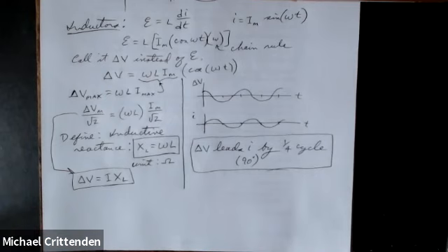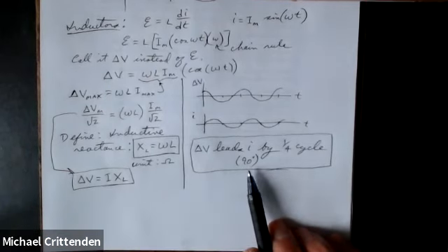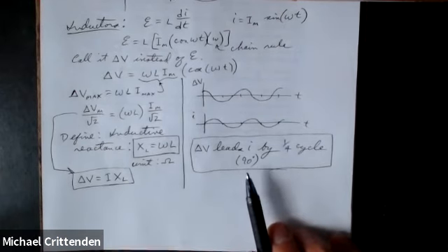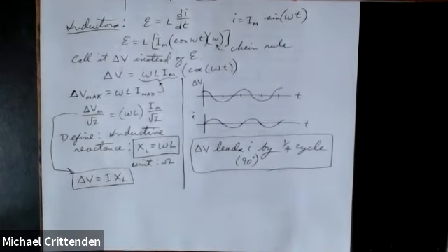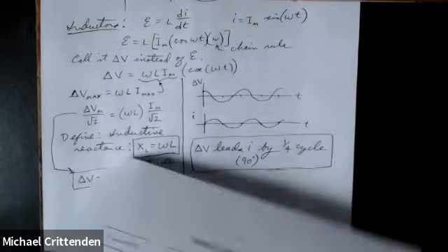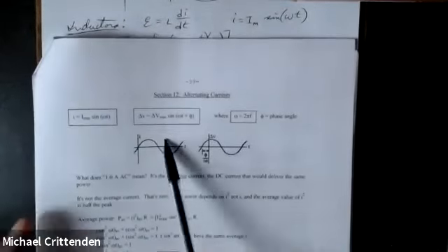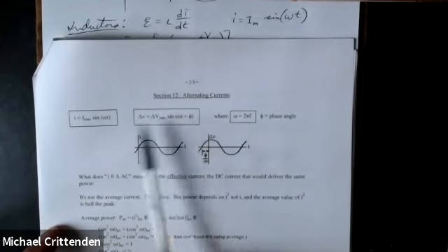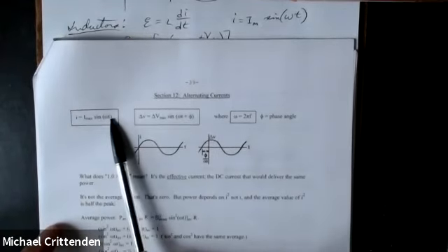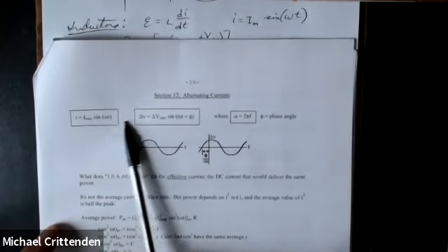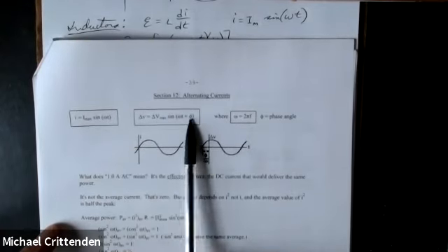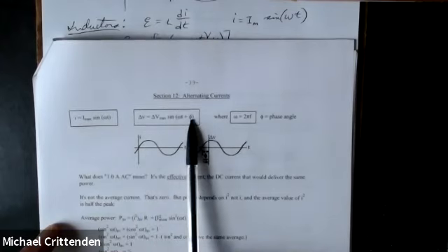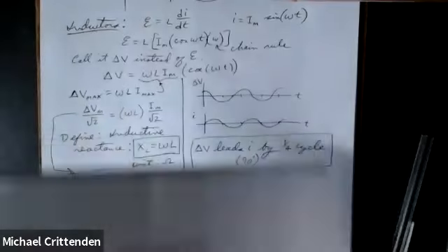In a resistor, the phase angle is 0 degrees. For an inductor, remember back at the very beginning, there was that phase angle right there, the phase difference between current, where I've built in a phase angle of 0, and voltage. If it's an inductor you're talking about, that phase angle is 1/4 of a cycle, 90 degrees.